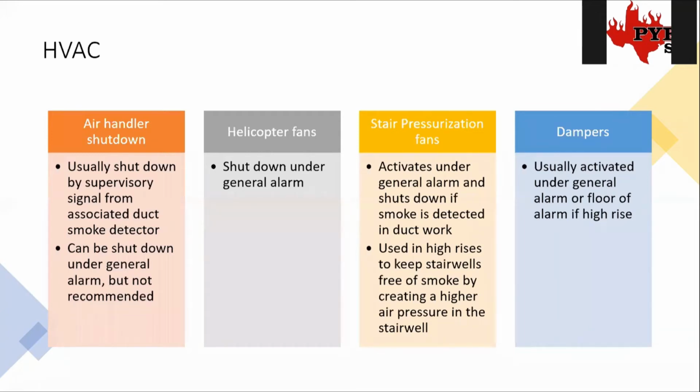But there are some places where they want it shut down under general alarm. We don't recommend it. When people say that, we try to talk to them and be like, hey, we don't recommend it. This isn't good. Old code had it be that way. So sometimes you'll run across old schools or something where all the units are shut down under general alarm. But that causes all kind of mechanical problems for them in the long run. So we don't really want to do that.